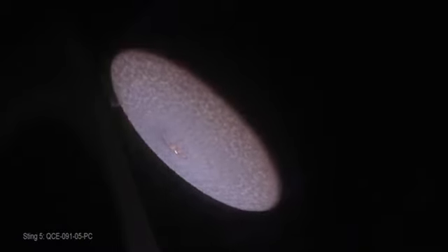And what you'll start to see in a minute is that there's actually a little bit of melt flow. You can start to see these little waves developing on the edges of the coupon where there are some shear forces. So we're actually melting those quartz fibers just a little bit, so we know we're over 1700 degrees Celsius at that point. In order to achieve that, our instruments tell us we're closer to 2100 degrees Celsius there. In the center, you start to see a bright spot, and that's the instrumentation plug. We're actually slowly ablating through this material a couple of millimeters to reveal the underlying instrumentation of the article.